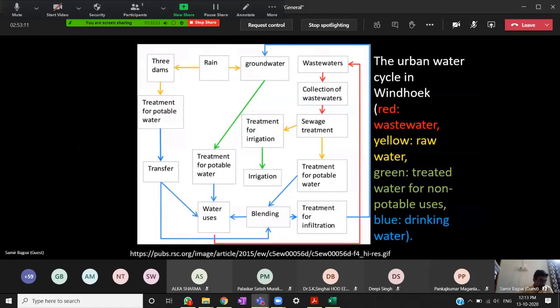Every year, if you look at the Groundwater Board report on quality of groundwater in India, every year more and more people are being exposed to poorer groundwater quality. Arsenic concentration is increasing in more areas, fluoride concentration is increasing in more areas, iron and manganese concentration is increasing in more areas. And more districts of India are coming into this. Why is it happening? It's not that you are knowingly putting something in your groundwater. It's because of poor management of waste, overall poor waste management. And the second reason is over-exploitation of groundwater.